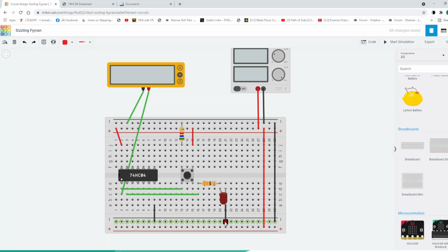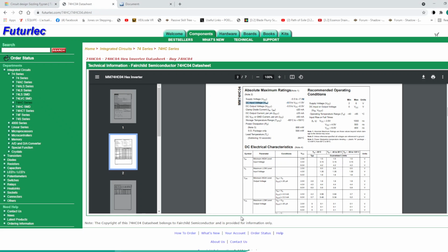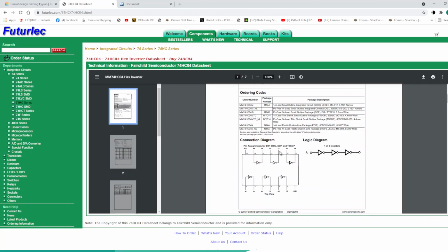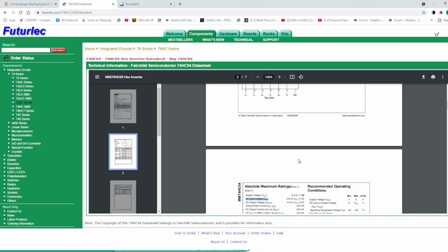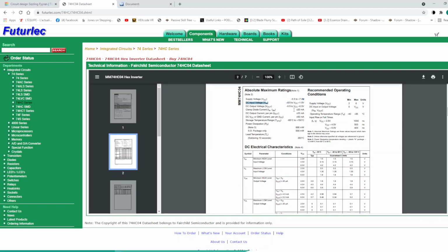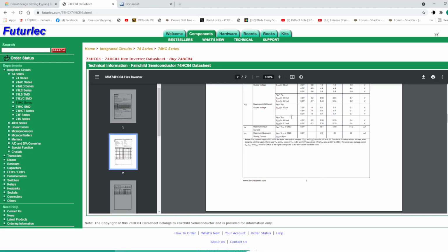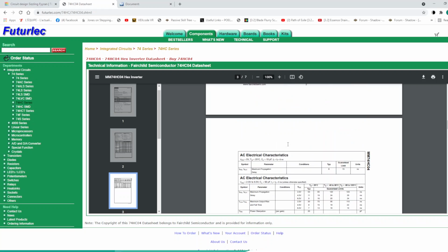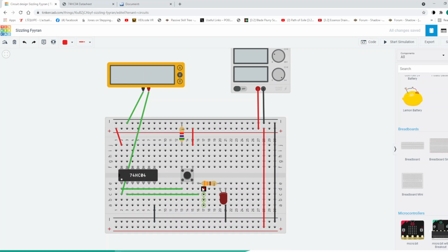Okay, so it refers back to the fact that the manufacturer left an operating range of voltages for this IC. Okay, so we don't use the data sheets very often, but we use them to know the pin layout, and if we have issues to figure out the voltages needed for things to work correctly, as well as the current sourced and sunk into the IC, as well as much more rarely the transient time or the temperature range of operation.